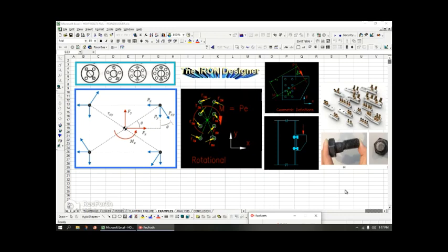So from the center of the bolt through the centroid, and then the reactions in the yellow arrows are acting opposite to the direction of the moment to resist the moment, and they're acting perpendicular to the center lines drawn through the centroid. So this is just one diagram showing you only torsional or moment, basically. The one to the left is showing combined load, moment, and directional loads.